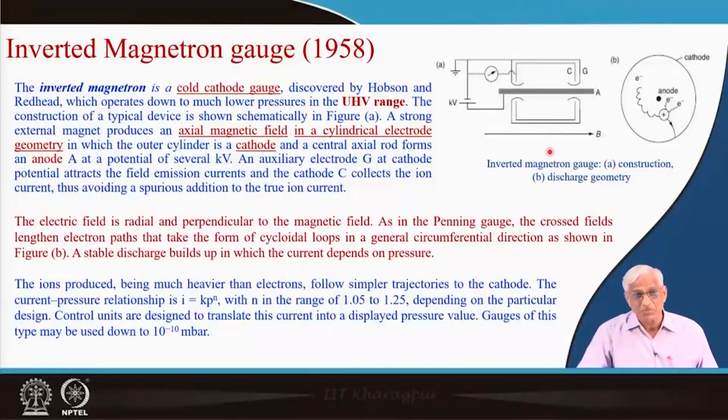So, these initially produced electrons should do their duty of ionization, but they should not be collected by the same collector cathode. They should be collected somewhere else. If these electrons interfere in the outer circuit with this anode and cathode, that is dangerous. So, some other electrode should collect these electrons and ground them. That is why they created one ground electrode.